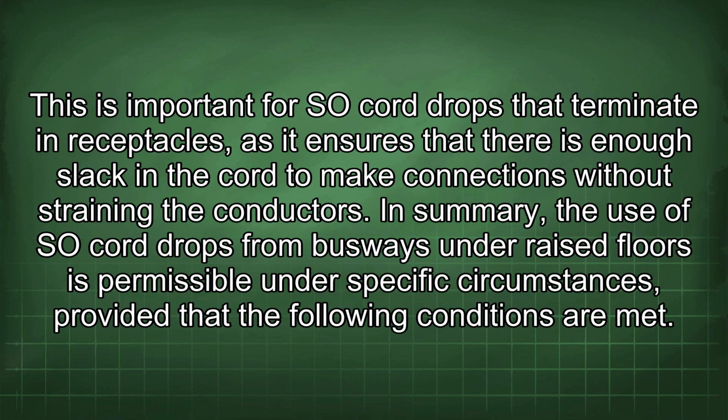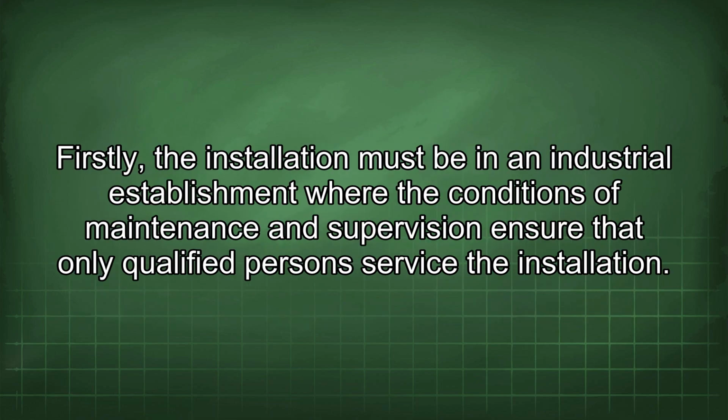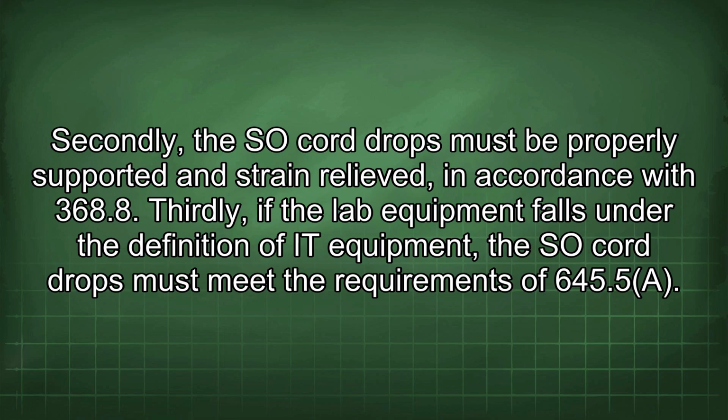In summary, the use of so-called drops from busways under raised floors is permissible under specific circumstances, provided that the following conditions are met. Firstly, the installation must be in an industrial establishment where the conditions of maintenance and supervision ensure that only qualified persons service the installation. Secondly, the so-called drops must be properly supported and strain relieved, in accordance with 368.8.